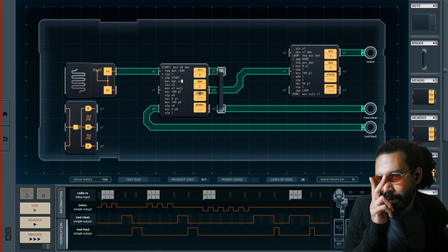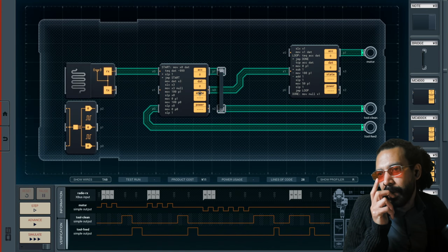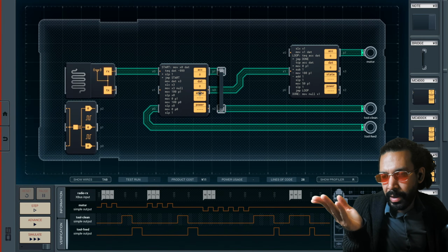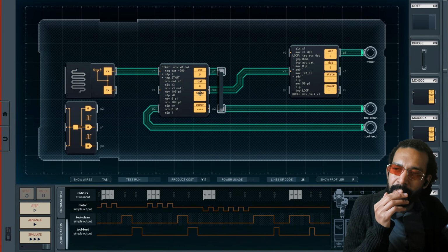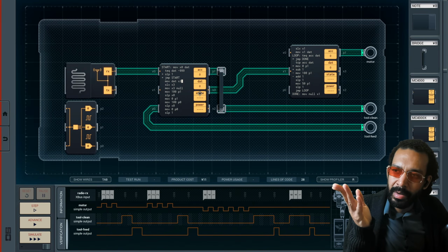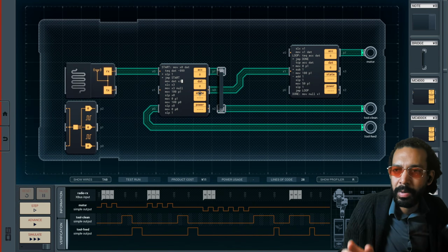Accumulator still needs to be updated properly to 2. Oh, right. So we save what we get from the data packet to the accumulator value, and we jump, and then we sleep the absolute value of the difference between the previous accumulator value and whatever we just put into the data register.